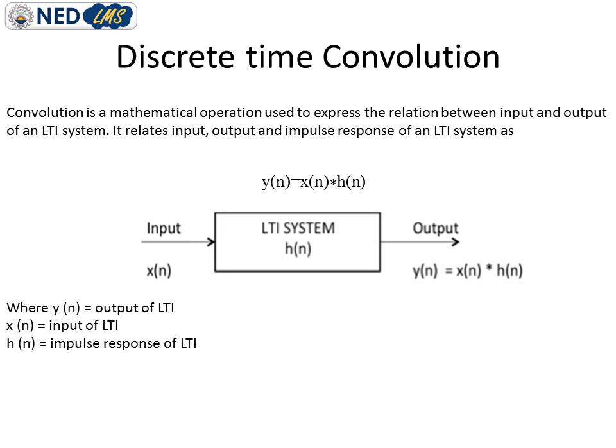An input signal enters a linear system with an impulse response h of n, resulting in an output signal of y of n. The mathematical expression is x of n convolve with h of n to yield y of n. In words, the input signal convolves with the impulse response to make the output signal.